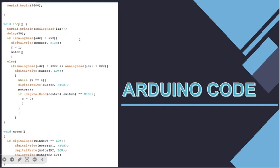Now we have seen that in general cases, when the laser is falling on the LDR, the value of LDR is typically in between 800 to 1000. So that means in the second case, you can see that we have placed the value between 800 to 1000 as buzzer low, that means it is the normal condition, and in these cases the buzzer will not be activated.